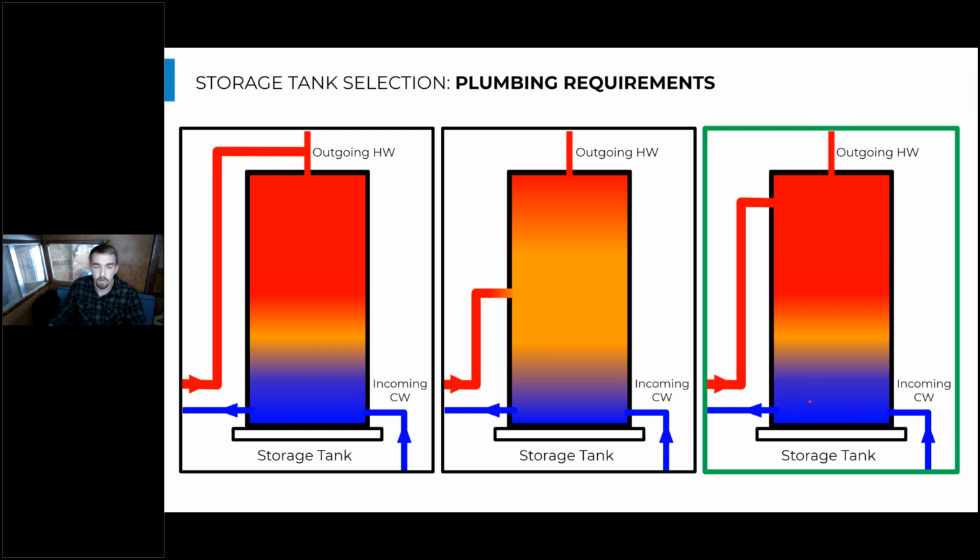Then we can pull that cold water out with our heat pump water heater, heat it to a high temperature, and eject it to the top of the tank. So we have a really nice separation of hot and cold, with a small layer, which we call a stratification layer, between the hot and cold volumes of water. Now this heat pump is always seeing cold water until this tank is completely full of hot water.